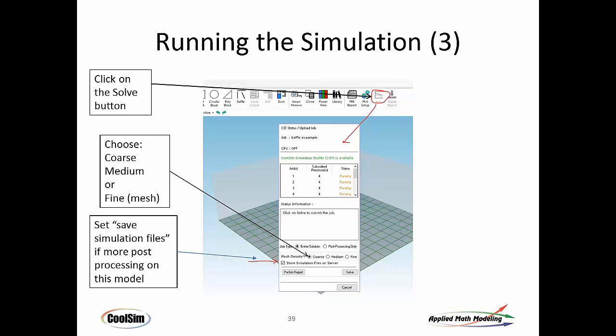I did just get a question about what is the mesh method that we use in CoolSim. CoolSim is a hex dominant, body-fitted hybrid non-uniform mesh. So it is hex core. It uses hexes wherever it can, but as it gets close to angled surfaces or round surfaces, it will switch to tetrahedras and or prisms, mostly tetrahedras, on the surface, so that you get a nice close body fit on anything that's got a non-regular, non-hex shape, such as an angled wall or a round object or whatever. The technology is quite good.